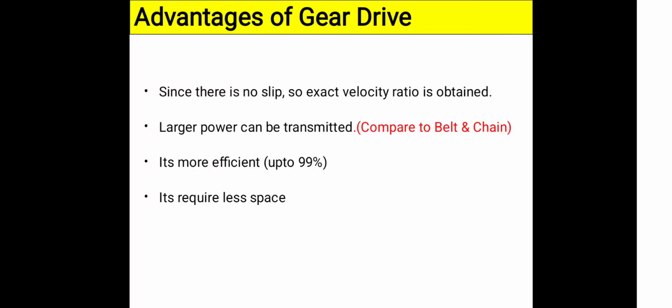Another difference of these non-parallel non-intersecting gears is that only the worm can be the input, and the worm wheel acts as the output gear. We are not able to transmit the power from the worm wheel to the worm, so it can transmit the power and rotation in one direction only.